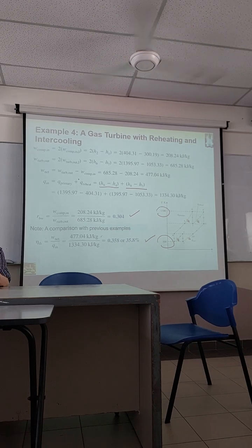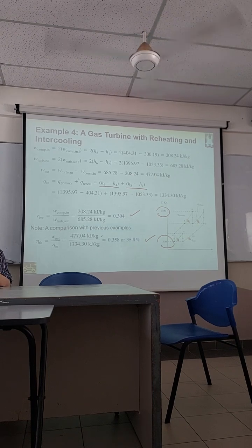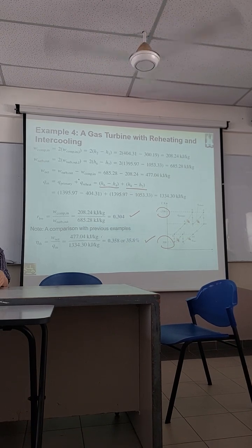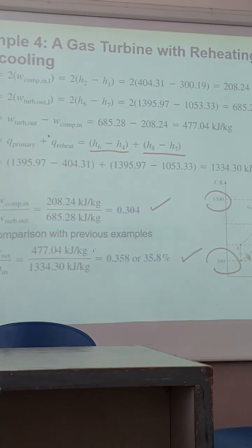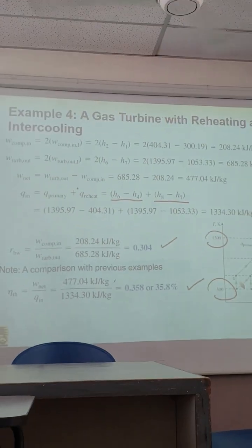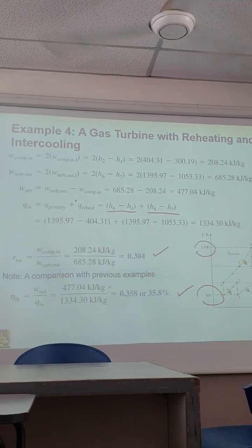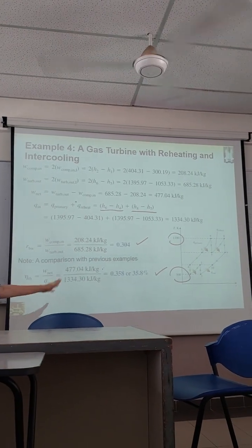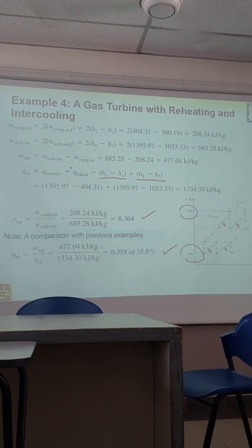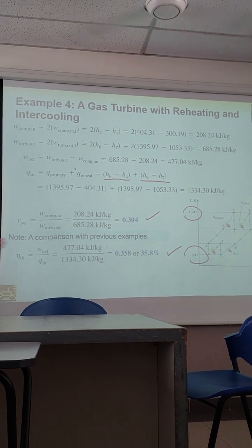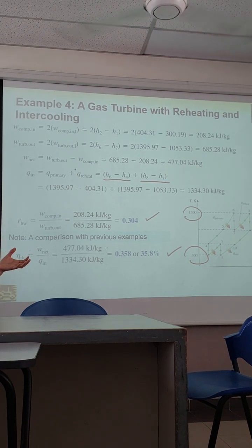Okay, so this is part A. Then part B, we incorporate a 100% effective regenerator. When we add the regenerator into the system, unlike the Rankine cycle, it actually doesn't affect the turbine output or input, because you are just using the exhaust. You didn't purposely channel out a portion of the gas.